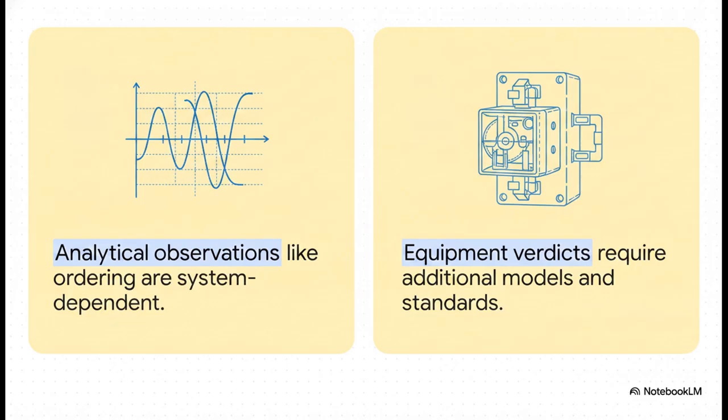A purely phasor domain fault result does not magically set a protective relay, select a circuit breaker, establish an interrupting duty, or calculate an arc flash exposure. Those high-stakes decisions require entirely additional models, deep system data, strict adherence to standards, and highly accountable engineering review. A truly defensible answer makes that boundary explicitly clear.